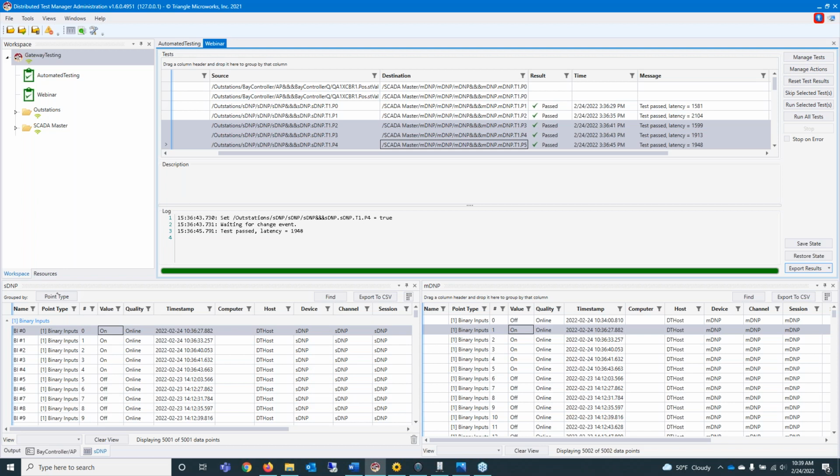So when we plug a SCADA data gateway or any sort of gateway, data concentrator, things like that, into our simulated environment, as far as it's concerned, all of the upstream and the downstream devices are physical devices. Likewise, if you just have a Modbus master or DNP master or whatever, if it hooks up to a simulated outstation slave server, whatever it is inside of DTM, as far as it's concerned, it is an actual physical device, and you can test that just as easily.